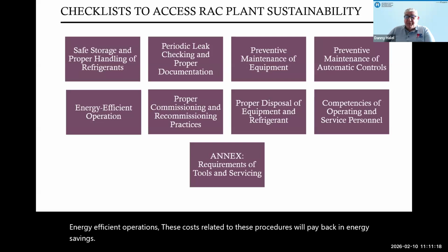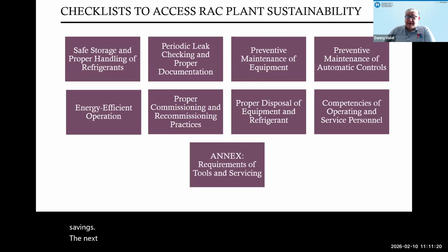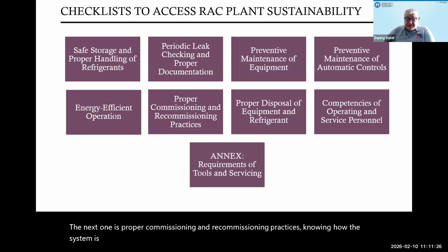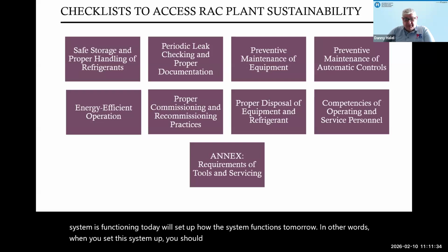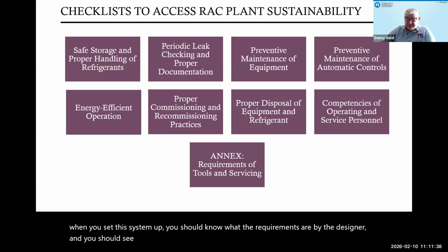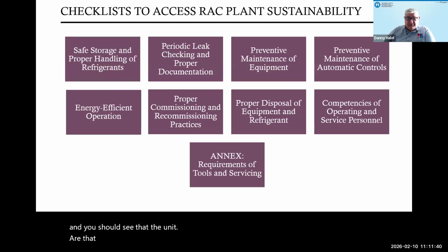The next one is proper commissioning and recommissioning practices. Knowing how the system is functioning today will set up how the system functions tomorrow. In other words, when you set this system up, you should know what the requirements are by the designer, and you should see that the system is functioning at that level before you release the unit to the owner.